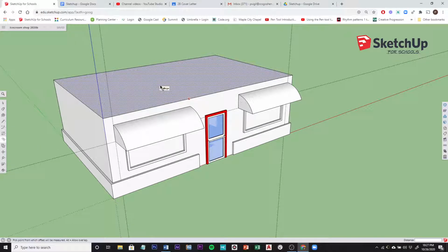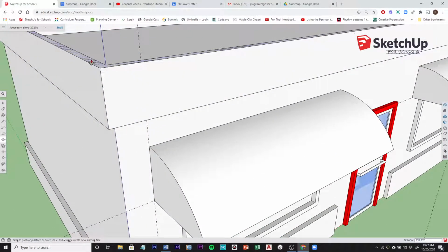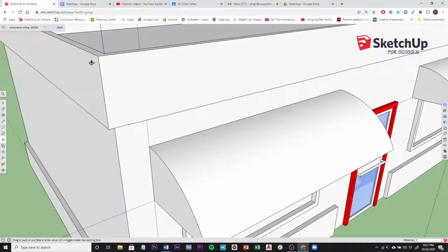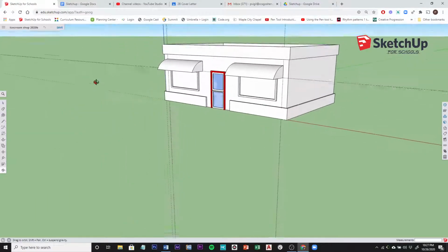We're going to click on the top rectangle, anywhere inside there, and we want to offset on the outside by 3 inches. 3 quotation mark, enter. Then we're going to push-pull this up 2 feet. Just this trim border here, click on that, drag in the upward direction, and then type 2 apostrophe enter. So now we have a nice top trim there.